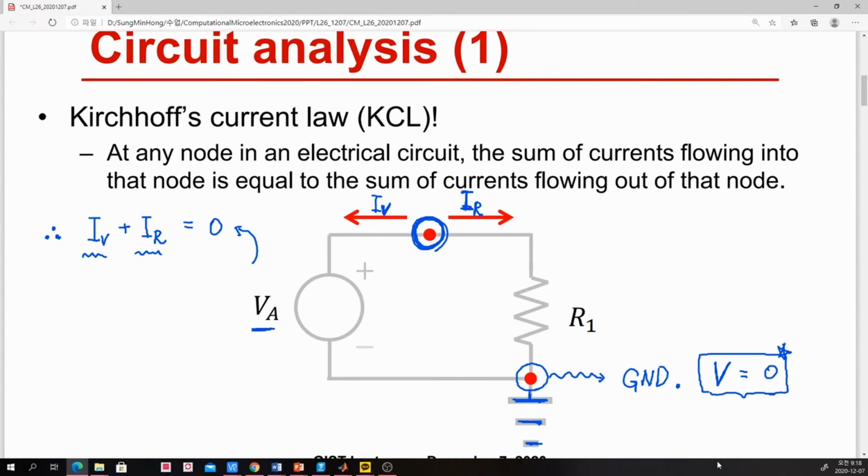So this is still an undetermined system, so we need certain equations. How can we supplement this Kirchhoff's current law? You know that we have not applied the nature of our voltage source and resistor. So quite naturally, we can say we need to introduce two more equations, one specifying the voltage source and another one specifying the resistor.